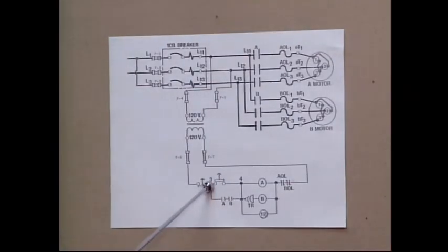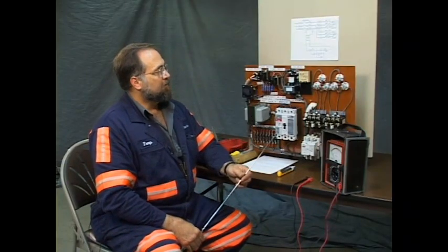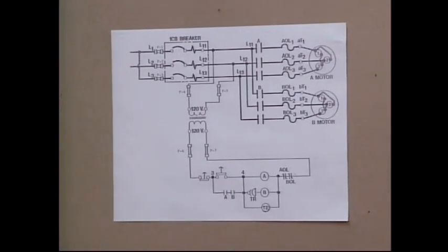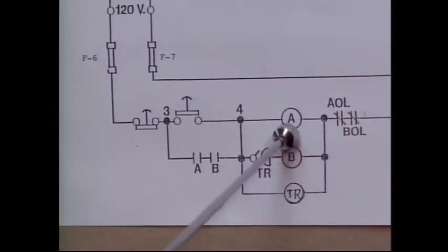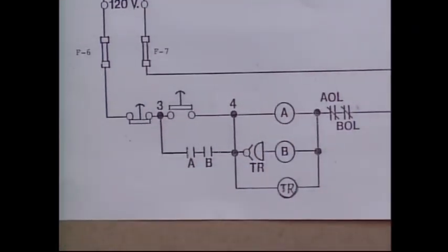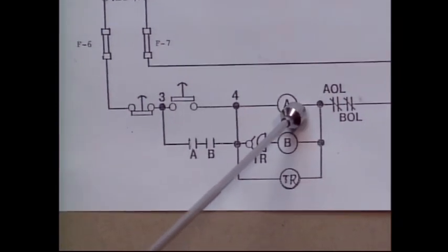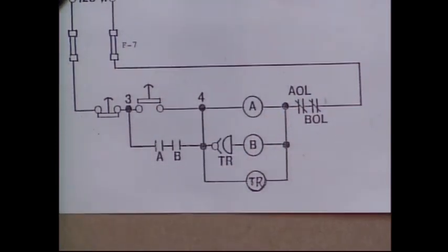We spoke earlier of the holding circuit. Some folks illustrate that as a sealing circuit, holding circuit. They mean the same. But if you see on the drawing, you have a normally open momentary start switch. When you depress the switch, you energize the remainder of the circuit. And when the circuit is energized, when A contactor pulls in, A coil is energized, it has a circuit, A contactor closes, A auxiliary also closes.